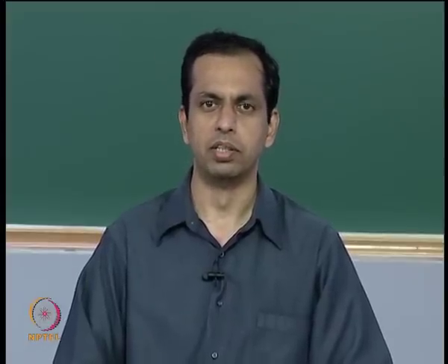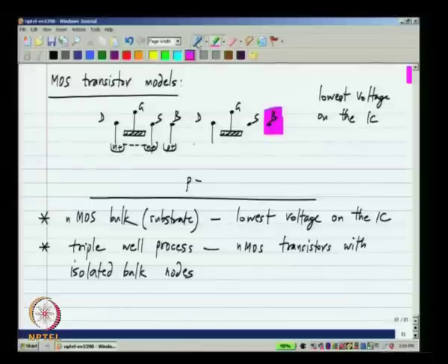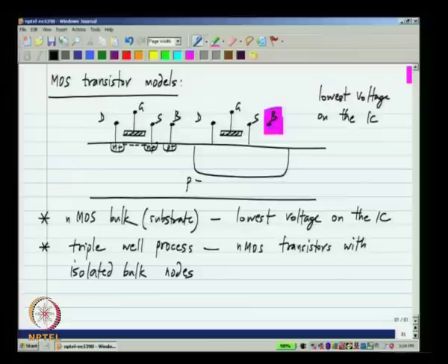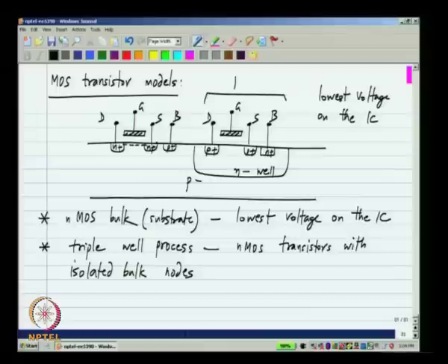Okay. That is something to keep in mind while designing the integrated circuit. Now, we can't design with only NMOS, or we could, but the design would be rather inefficient. It is better to have both NMOS and PMOS transistors. To have PMOS transistors, we have an N well, and inside that you make the P plus drain and source connections, and you will have a PMOS bulk connection to the N well. Okay. So, this is a PMOS transistor and that is an NMOS transistor.